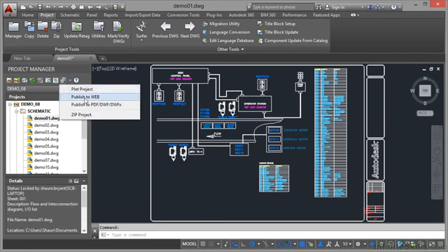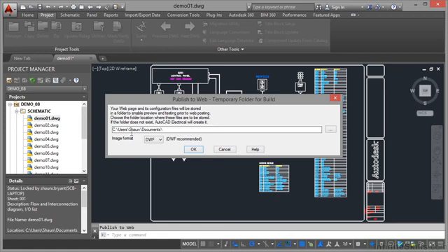If I want to go out to, let's say, the web, what'll happen there is it'll ask me where the folder is going to go with the images that I'm plotting. So I can plot out to the regular sorts of images, DWF, JPEG or PNG. They're all web-based. I select what I want, specify a folder where they're going to go, and then I hit OK. And what'll happen then is all those DWFs, JPEGs or PNGs go to that folder, and they can then be utilized on the web. Now what will happen is it will put it into a temporary folder for building. And then what you do is you then go and suck those into your website using whatever tools you might use. I'm not going to do that, so I'll click on cancel there.